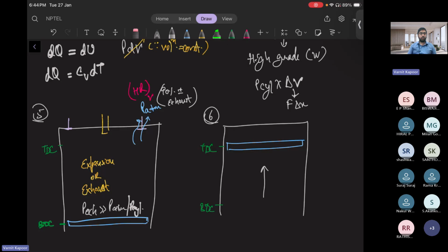Okay, and this is your exhaust stroke because it carries the inertia as well. Because of the inertia, the piston is moving to the top dead center from the bottom dead center after your power stroke. So finally we can say that the remaining 10% goes out, and the valve will still remain open. The exhaust valve remains open, whereas the inlet valve remains closed. You don't want the fresh air-fuel mixture to also enter and exhaust out. That would be a leakage of your fuel, which you don't want. So the remaining 10% of the gases go out.